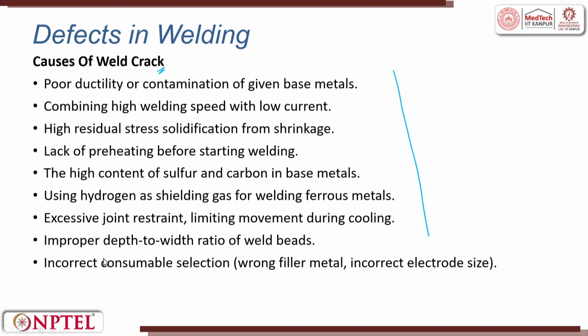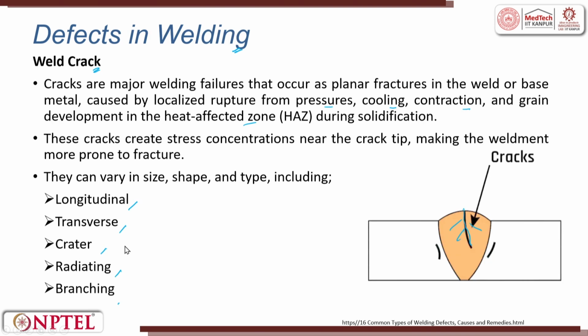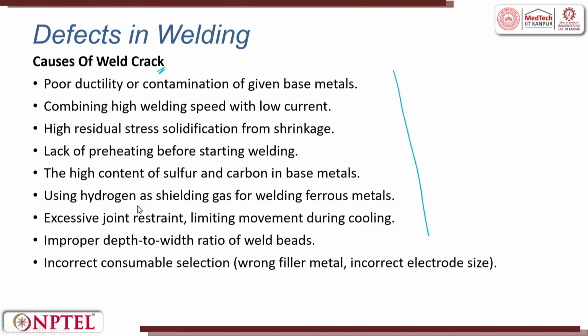Weld cracks, as you know, can happen in the longitudinal direction or in the transverse direction. Longitudinal is along this direction. In the transverse direction, it can be a radiating crack or a branching crack. So it is a combination of the process, the choice of material and the filler.